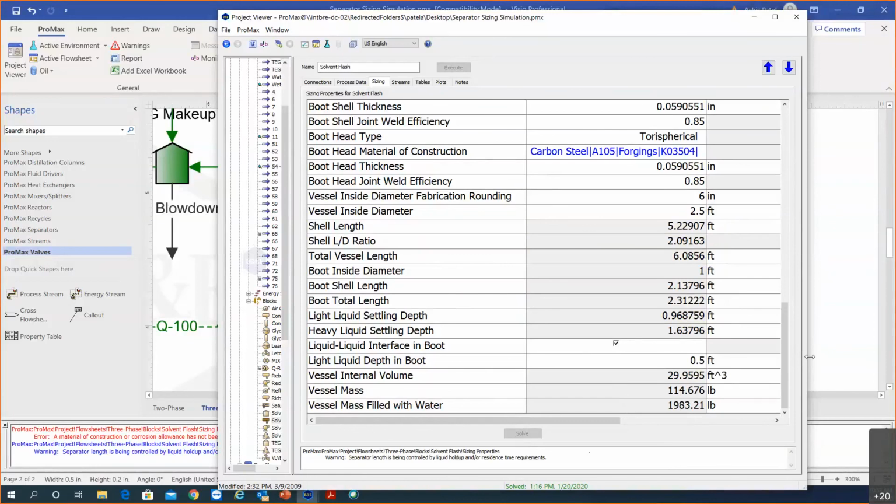And this is because now that we didn't actually need that extra liquid bucket to hold our light liquid, we would have had, if we just gave more space to simply the settling compartment, that would give enough space for the heavy liquid and the light liquid to separate out appropriately.